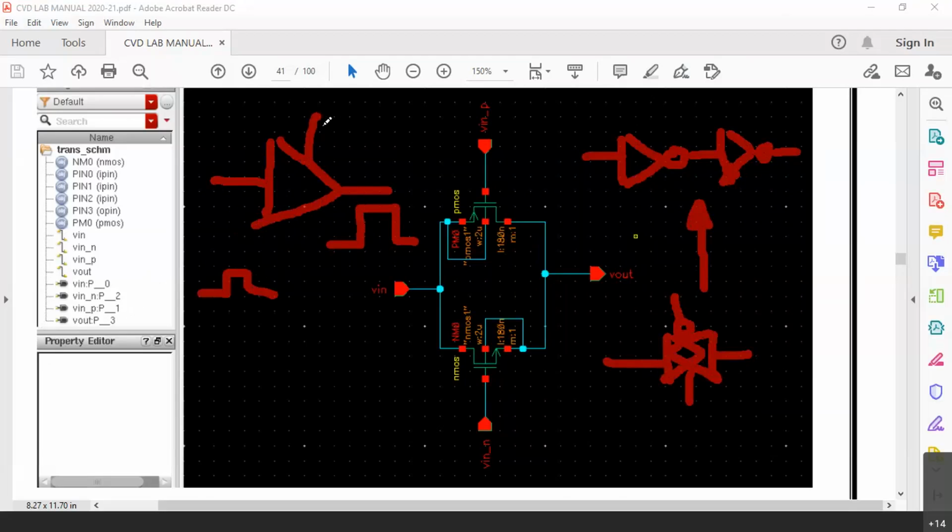How? Because the buffer has a VDD and a ground. So when the input signal is coming inside the buffer, it is going to take the power from the VDD. Even in these inverters, there is this VDD and ground, for both of them. Whenever the input signal is coming, you have to visualize the inverter with one PMOS and NMOS there.